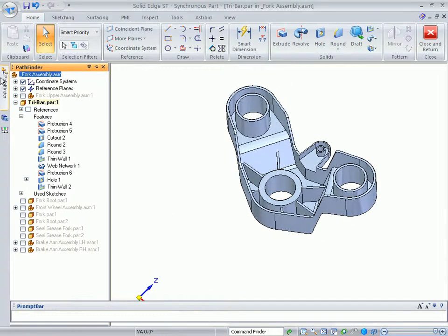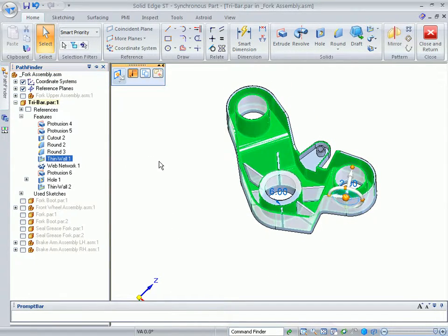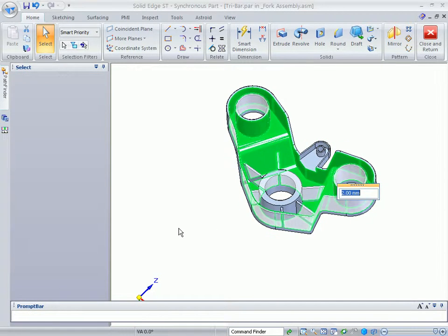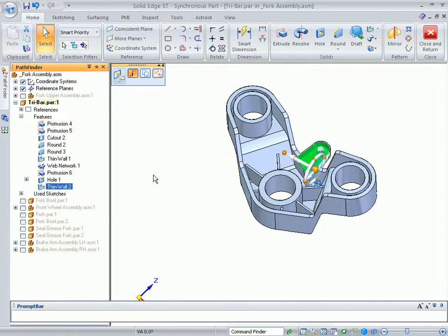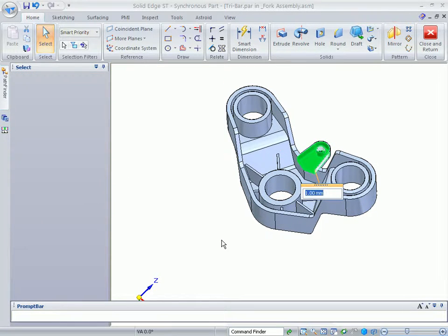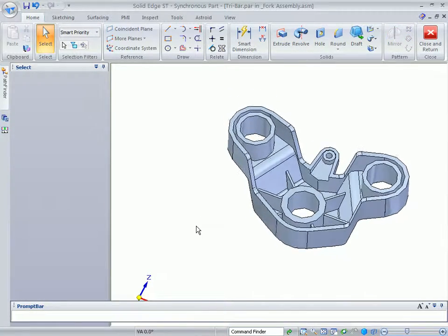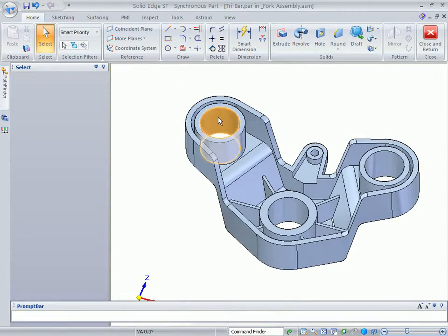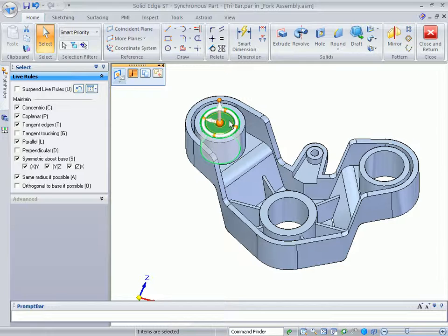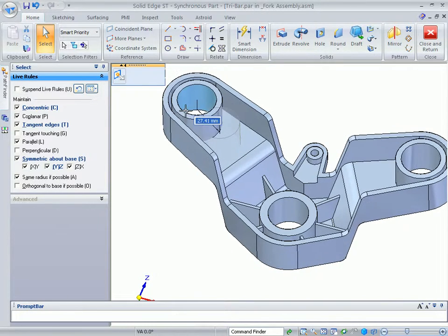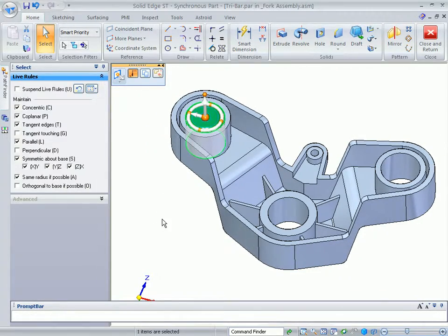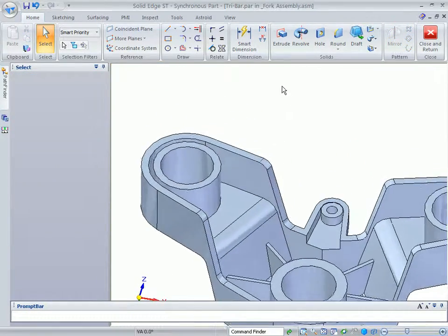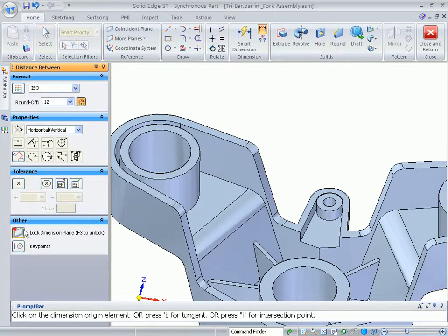Thin wall operations are procedural, so you still have edit control without complete model regeneration. Watch as we change the wall thickness and the model instantly updates. Because of this technology, larger, more complicated models will also update with the same nearly instant speed. To further demonstrate this fast performance, let's make a change to the entire model. Since the part is just roughed in, we can modify the arm by moving one of the original mounting holes. As the edits are made in real time, see how the model stays symmetric and the wall thicknesses are maintained.